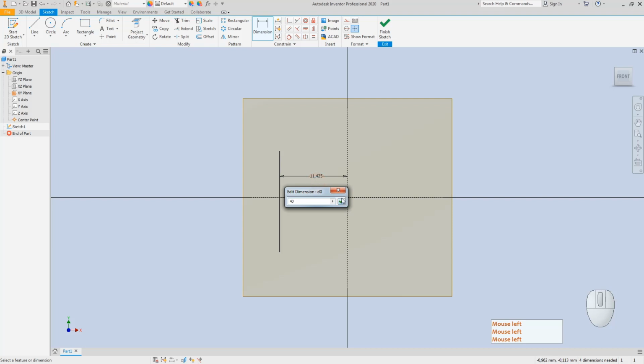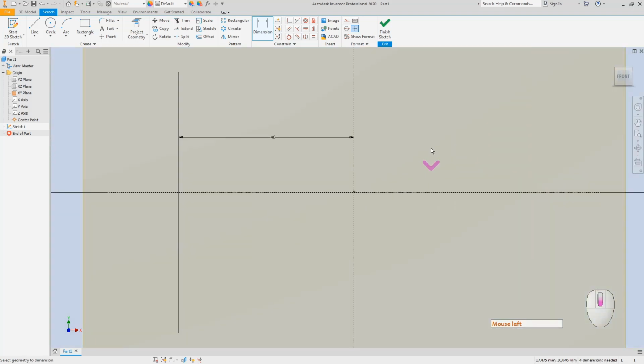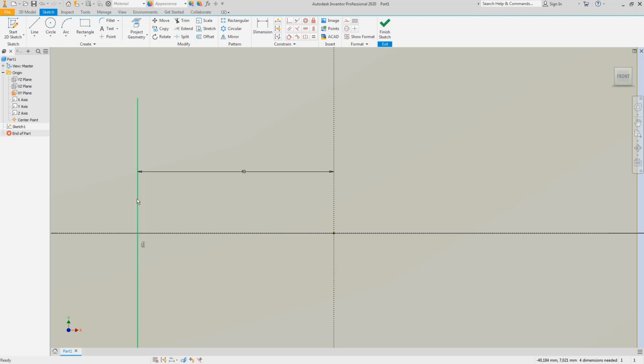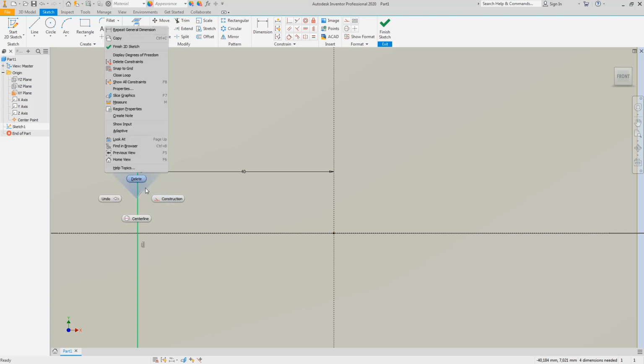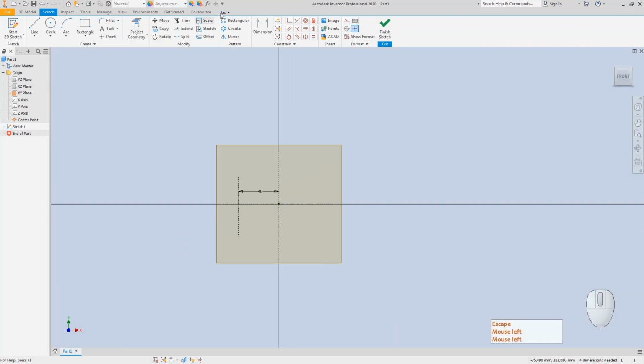these 2 points, which is this line, about the 40 millimeter in distance. I will also not going to use it in the extrusion purposes. I will just convert this line for construction. I will have the other line, or if you can, by the mirror tool, or I will just make a new line on the other side and convert this with the construction purposes. Also, I will define this dimension with 40 millimeters.